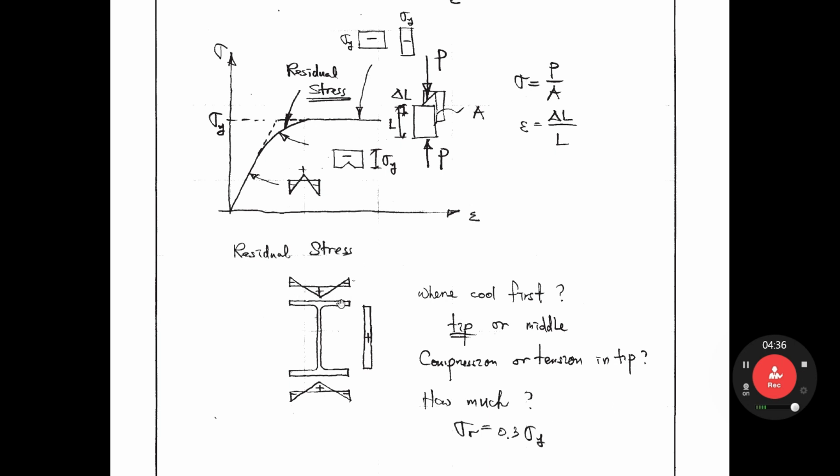If we see the stress state of this flange, as stress increases, somewhere here we can draw the stress diagram. It is convenient to think from this. Add the stress here, then the stress diagram looks like that. So this part is yielding. This center part is in the elastic range. This part, both sides, has the yielding stress.